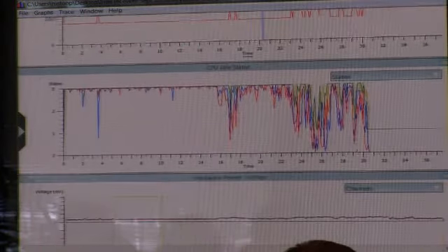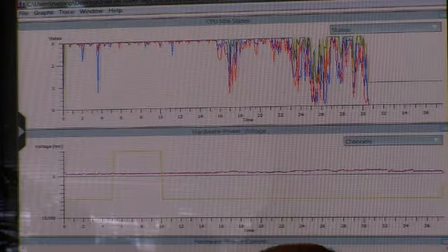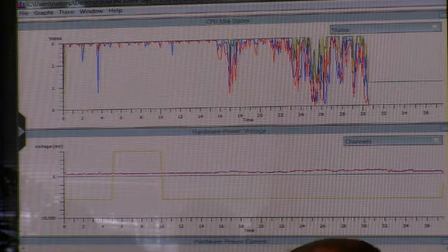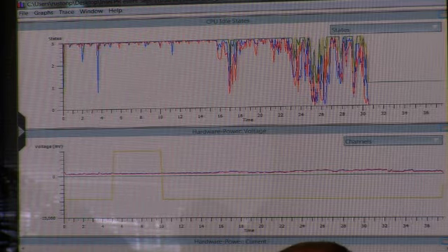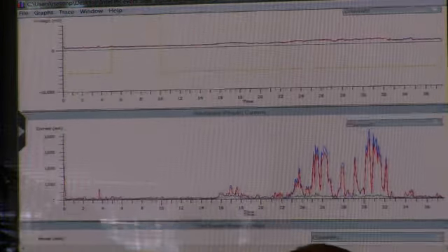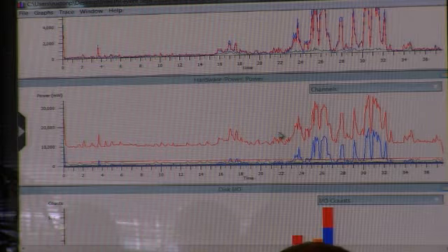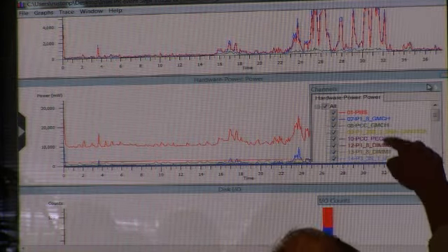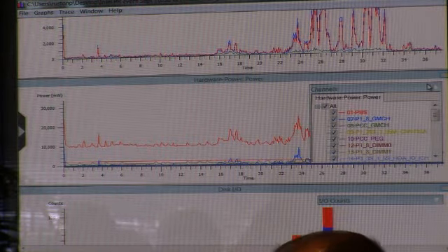The next graph down is the idle states. So I talked about C6. There are other power-saving steps that get you down to C6. And we can actually see for each of the cores that are part of the processor what state we managed to get it into. And then the next several graphs, I have a hardware voltage, hardware current, and then if you multiply those together, we end up with hardware power.